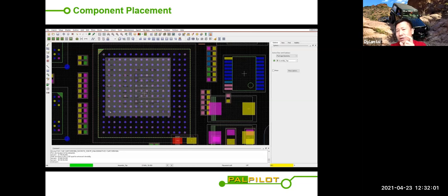You might be limited to a certain distance between one component and who it's going to communicate with. So placement has a lot of restrictions and considerations. And then of course your edge connector, like I mentioned on the previous slide, if a mechanical engineer already cut out a location where that connector is mounted to connect to your cables or whatnot, then that has a dedicated placement location.